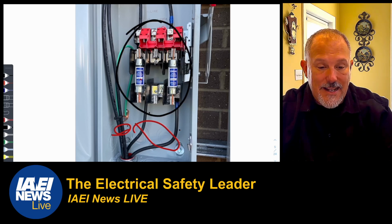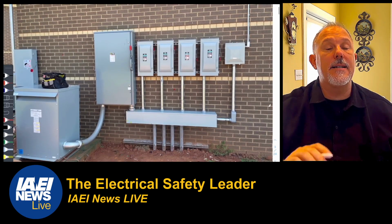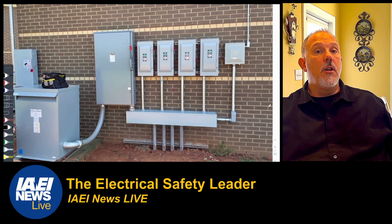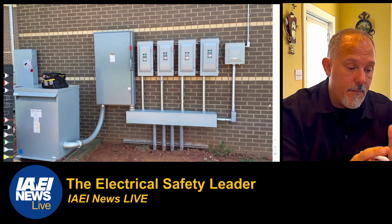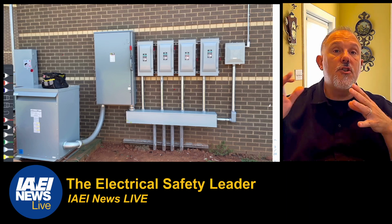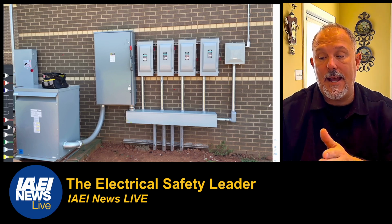And it's installed at a readily accessible location, complying with one of the following, and it's outside of the building or structure. So just like the transformer secondary conductor requirements, we're outside, and that gives us a lot more freedom than when we're locating these conductors inside. Because remember, these are unprotected conductors at their source. That's a big deal. From a short circuit protection, from an overload protection, there's an increased hazard because of the location in the circuit and because they're not protected at their ampacity at their source.